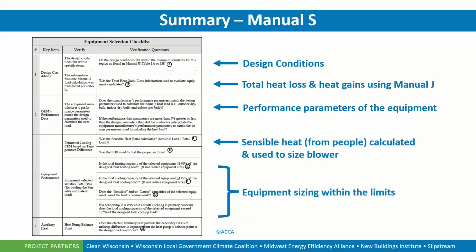When we look at that testing data as well as the manufacturer's design data to determine the heat loss and heat gain, or how many BTUs we can get out of that unit with that combination, and at what CFM. So does the furnace have a high enough output to overcome our heat loss? And can we get a blower speed, a fan speed? Can we deliver enough air at that BTU range that's required by the Manual J?